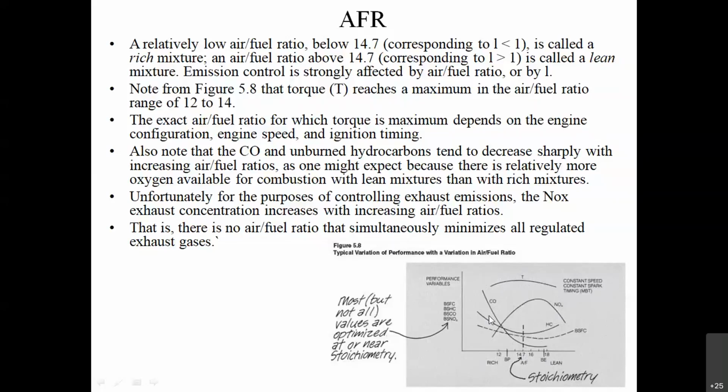That is, during combustion, what are the gases generated after combustion? You can observe at this particular level the amount of CO generated, whereas hydrocarbon is reducing. So from this graph we are getting a lesser amount of gases generated at stoichiometry, and this is representing your brake specific fuel consumption, which also we are getting minimum at this particular point.